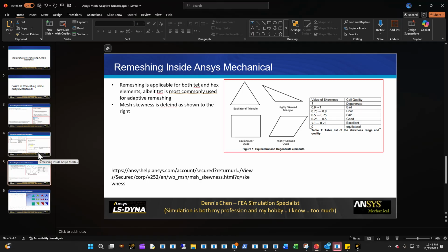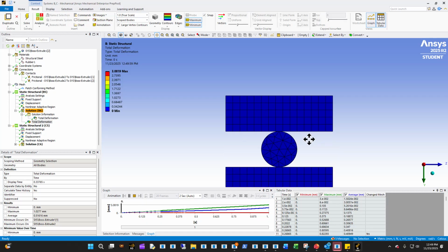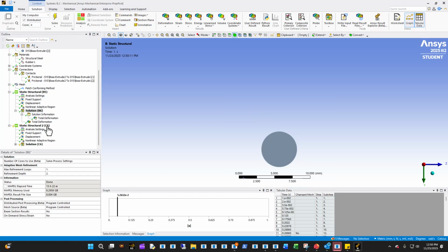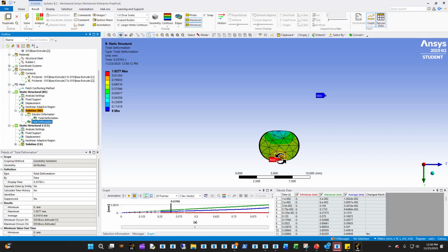In my opinion, this is much more useful in an O-ring compression type of analysis, because in an O-ring compression analysis, you do have a lot of bulk response, right? But also the area where the contact occurs is going to be really critical. So if I were to hide this to show you real quick, you can see that this area where the contact occurs is really important for convergence. So that's also where we'll want to mesh it a bit better.